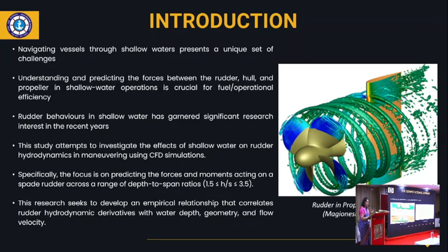The interaction between these two boundary layers gives the complexity of the problem and the effect of the bottom on the rudder. For the domain extents, we more or less follow the ITTC guidelines, as shown in the second figure. From the inlet, we put the center of the rudder at one chord length, and from the center of the rudder to the outlet extent is 10 chord lengths of the rudder.